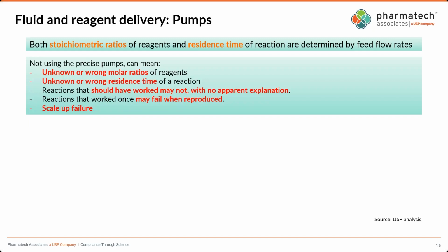However, this is only possible in continuous manufacturing if the variables of the reactions are accurately known. In this case, the reaction temperature, concentration, the stoichiometric ratios of the different reagents, or the residence time would be variables that could be important when you're developing a process.